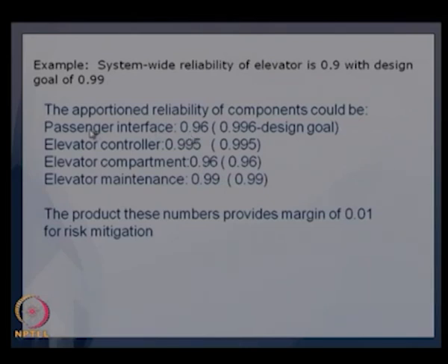If you know the particular component you are using, you have to use the reliability value provided by the manufacturer of this particular component, or if there are multiple systems coming in, we need to look at those systems and their reliability values and accordingly fix a value for this. Again, this is to be done by the design team. So, there is a little bit of subjectivity in this, but still it is a simple method. That is why it is used for the system requirements and allocation of the system wide requirements amongst the components. So, that is the way the apportionment method works.